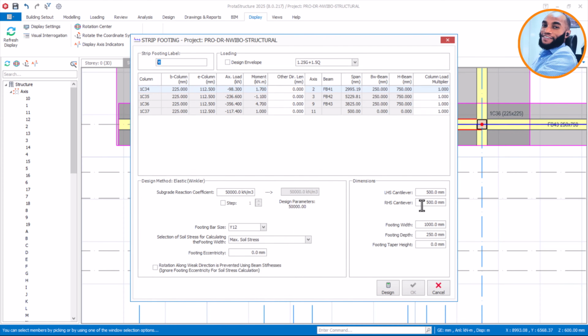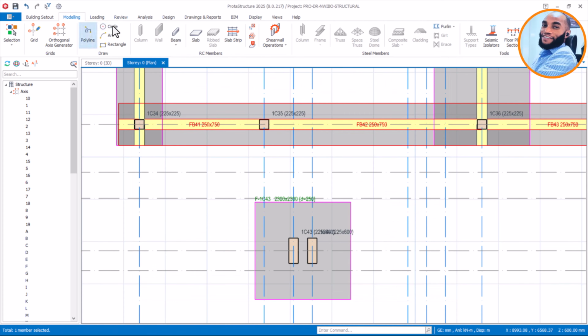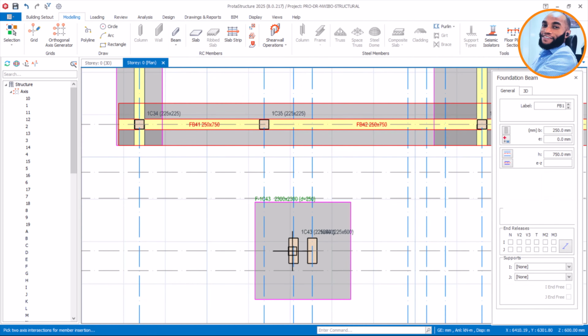It is just, sorry, not this. I would have to go and take beam from here. It is just to help chain this, to give more strength to the column. Yes, this pad base is already okay, but to give more strength to the column, I'll use a beam of what? 300. No, 450. I'll use 450, and then I can choose the width to be 225.